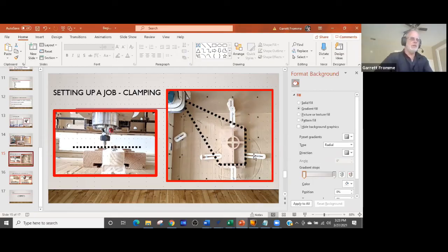However, it's a nice safeguard because I have had things move on me when I'm cutting, and sometimes you're running for 4 hours and then something happens and it moves on you. That's kind of a bummer. So I always try to clamp down at 3 points instead of 2, and I find that 3 points are almost always adequate for the size bits that I'm working with, which, well, I can't say I never work with anything bigger than a quarter, but if I'm using something like a bull bit that's 5/8 in diameter, then yeah, I'll go with 4 clamps. So, yeah, that was pretty much the summary.